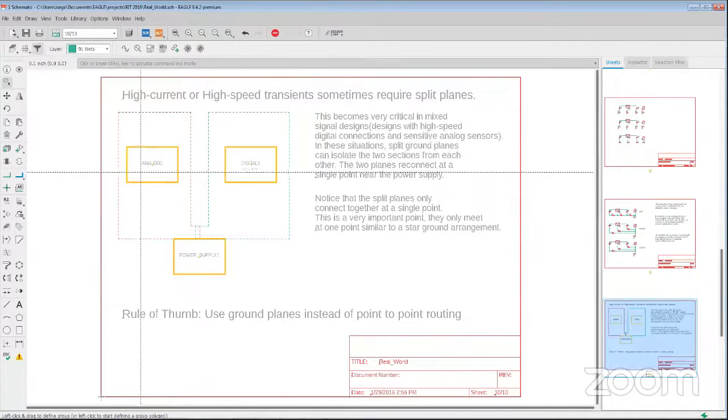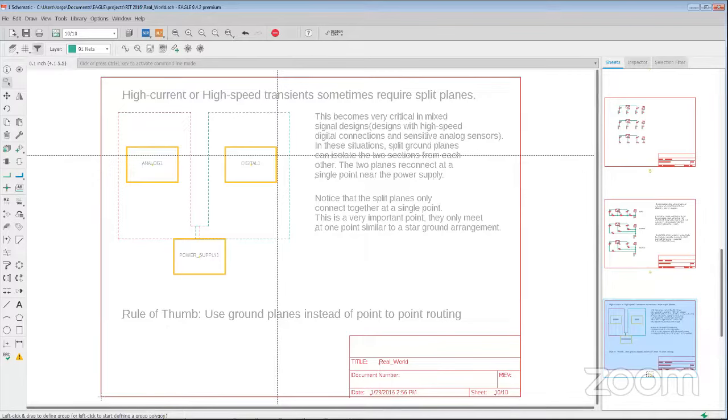let's say we have our circuit. We have digital. Digital circuitry tends to, again, a very broad stroke here, tends to be considered noisy because you have clocks. Clocks are square waves. Square waves have a lot of harmonic content. If they're going really fast, which they typically are because we're dealing with microcontrollers or FPGAs, then you have a lot of harmonically rich current going into the return paths.